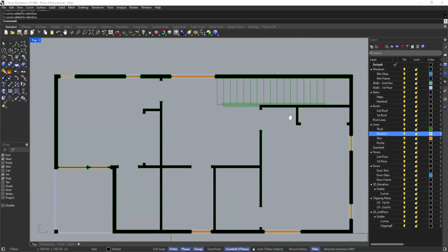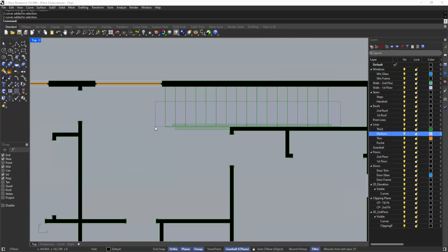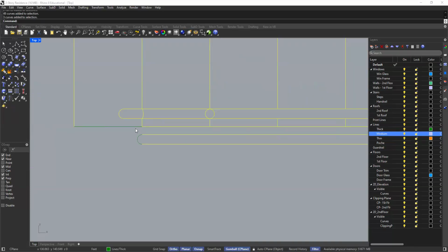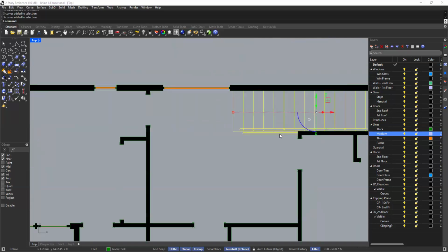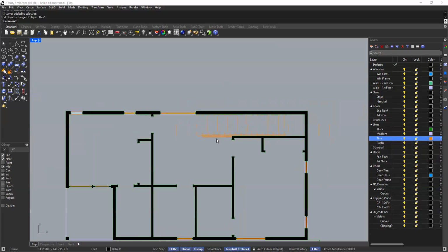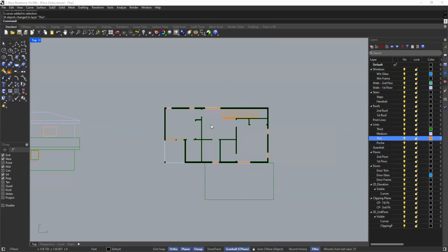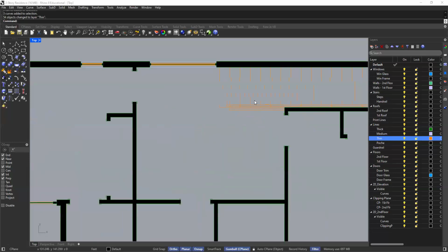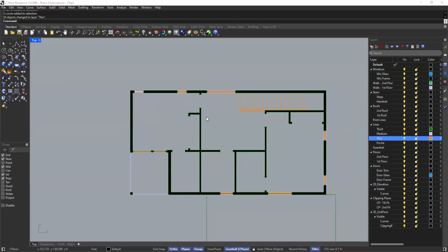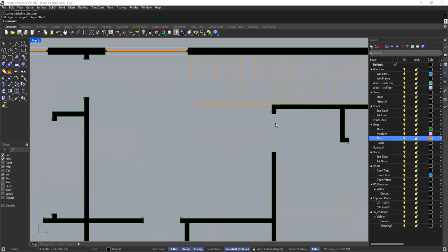The last thing I'm going to do is come over here and just do kind of a cross window around my stairs. And I'm going to see if we can select all this stuff. Put all of this in my thin layer. Change object layer. Okay. Now it could be that when I create the drawing itself, I could go in and say, you know what, this really should be thicker, these should be thinner, right? We do always have to take a look at the drawing and then make the assessment at that point of which lines need to be thicker and thinner in that way, right?